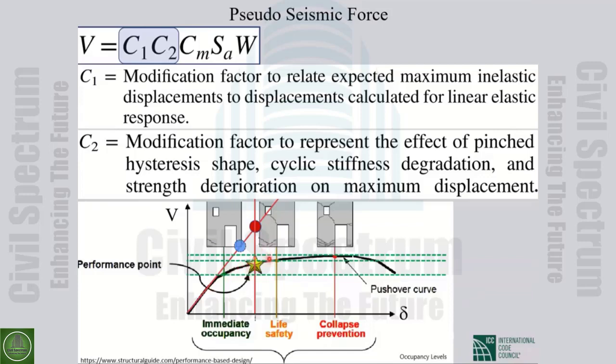So demand is dependent on the earthquake. We have different demands for different levels of earthquake. One earthquake can bring this building to here. So the demand is more than the capacity. It collapsed. It even passed collapse prevention, life safety, everything, as it collapsed. So this is the capacity, and at different levels of capacity, we have acceptance criteria for the different performance levels.